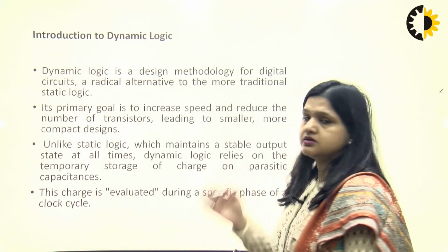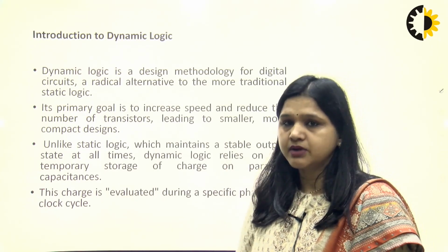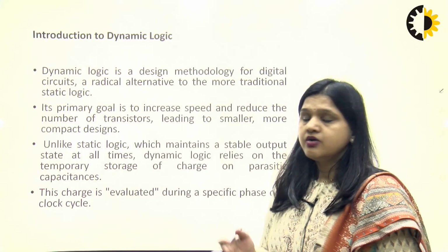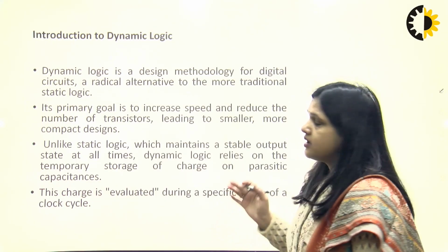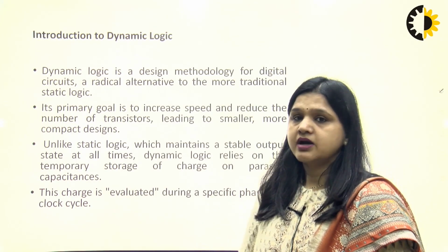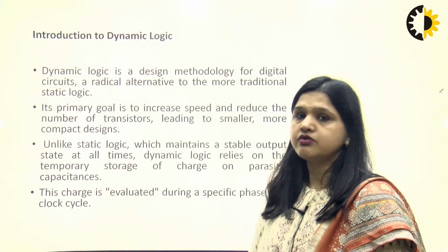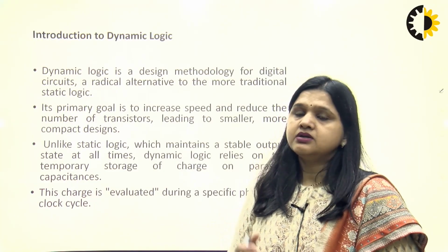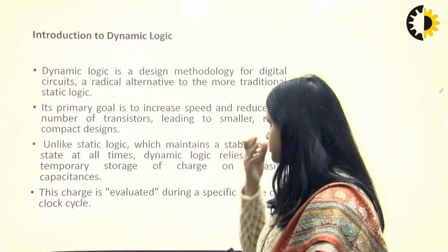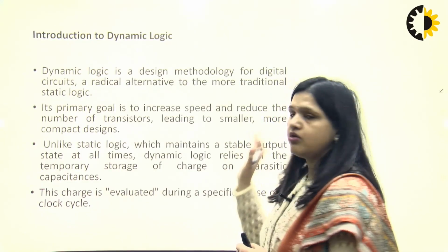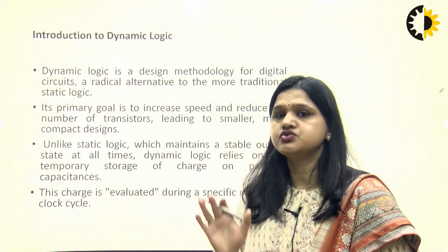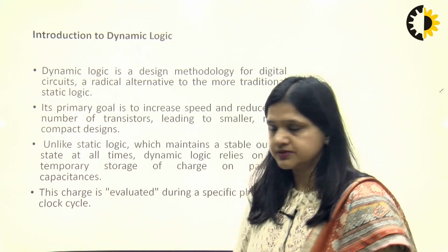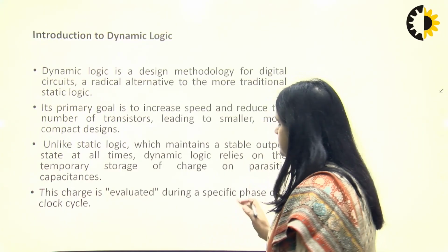So, first of all, let's see what is the dynamic logic design. So, basic dynamic logic design is a methodology for the digital circuits. By using the dynamic logic design, we can reduce the number of transistors in any circuit if we compare the design structure with the static. So, this is the primary goal of the dynamic logic design, to reduce the transistor count and hence increase the speed of the circuit.